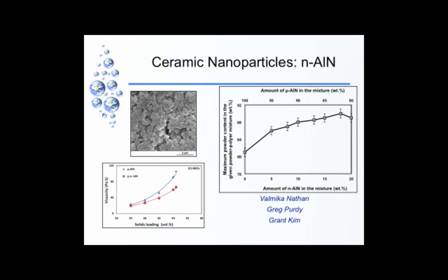So you have two possibilities now. You can either be at the same volume fraction of powder and just get better processability, or you can go all the way up to 72 volume percent, and so you can get much better structures in terms of controlling the dimensions when the material gets sintered. So you can control sintering shrinkage.